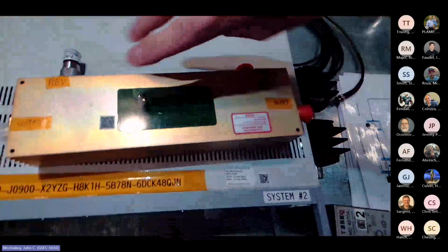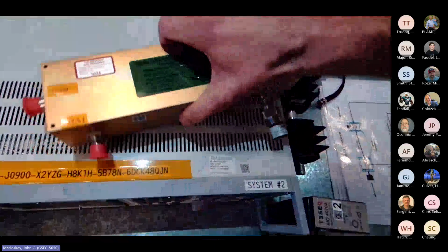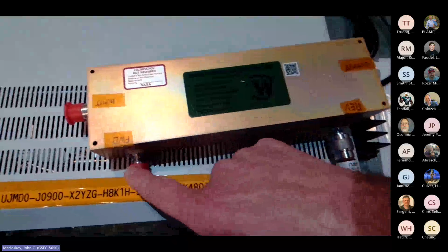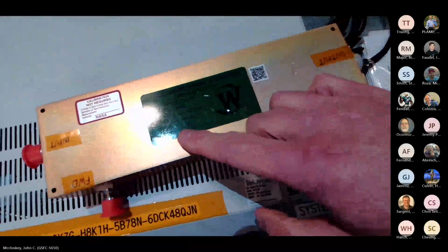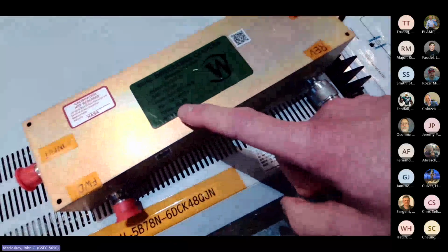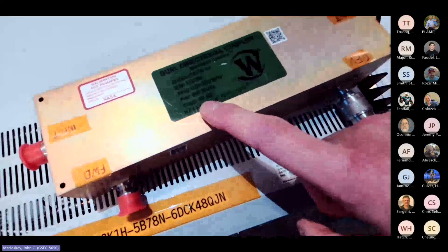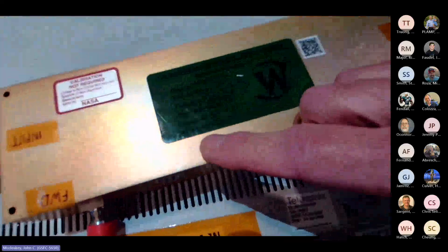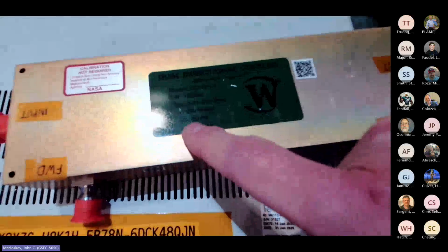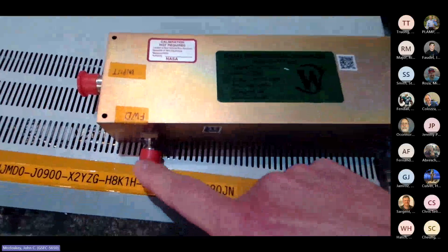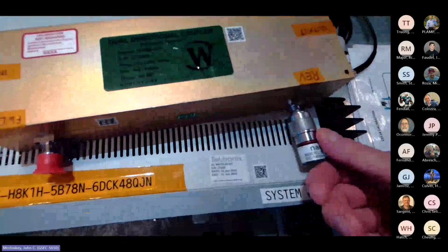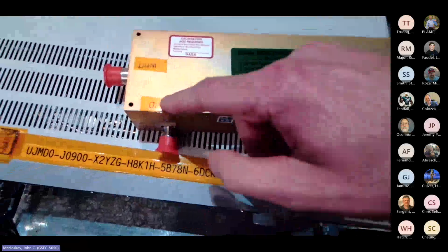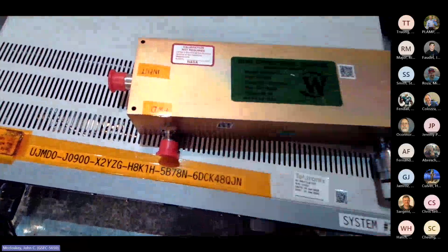And it does tell you what the attenuation is. When you're looking at one of these ports, does that say 40 dB? Yeah, that's what it looks like. All right, I have my glasses for when I'm actually going to need to see things here shortly. But yeah, 40 dB. So that tells you that when you're monitoring what's coming out of this forward power port or the reverse power port, that it's 40 dB down from the actual signal.